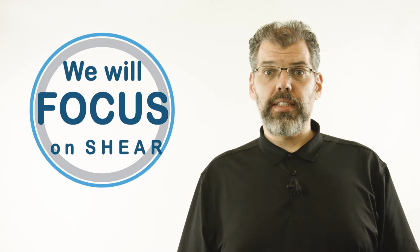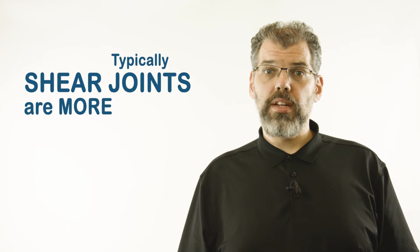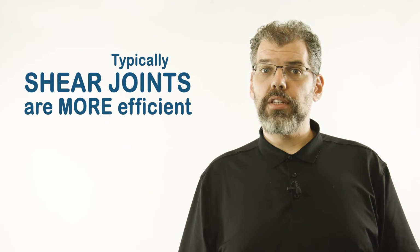Now that we have covered the basic types of fasteners and joint types, let's take a closer look at the possible failure modes in a mechanically fastened joint. We are going to limit ourselves in this discussion to mainly shear type mechanically fastened joints. This is not to say that tension joints are not important within the aerospace industry. There are numerous joint applications where a tension joint is needed, and these need to be carefully designed as well. But generally speaking, shear joints tend to be more weight efficient than tension joints, and thus are more frequently used.